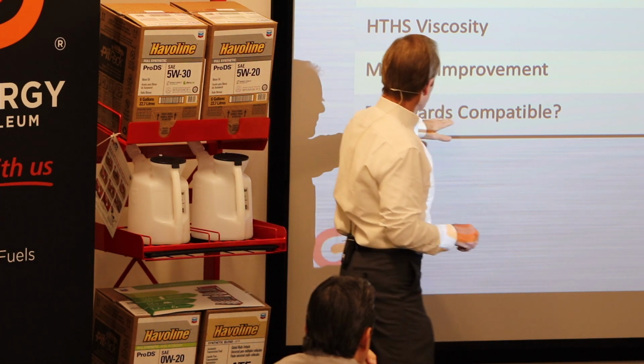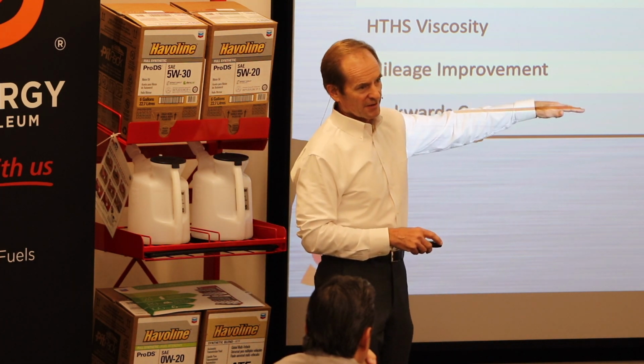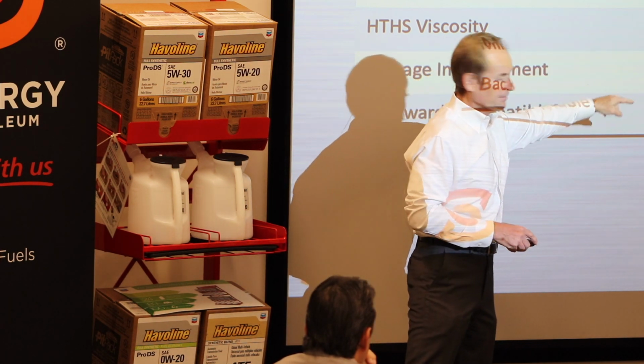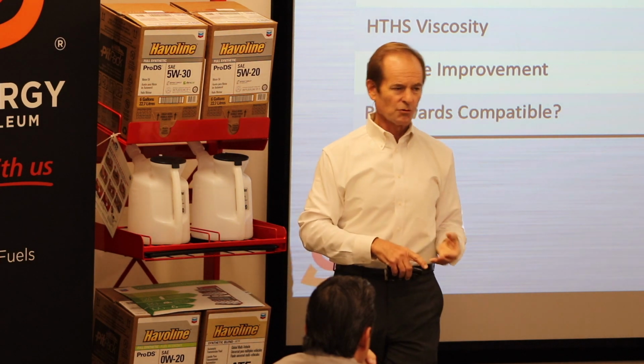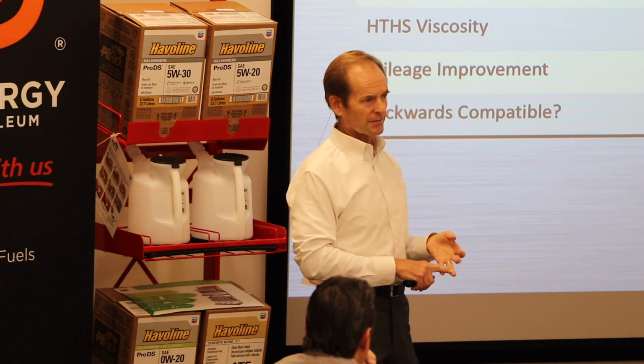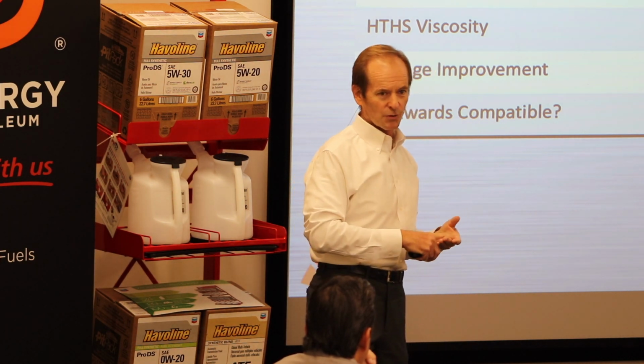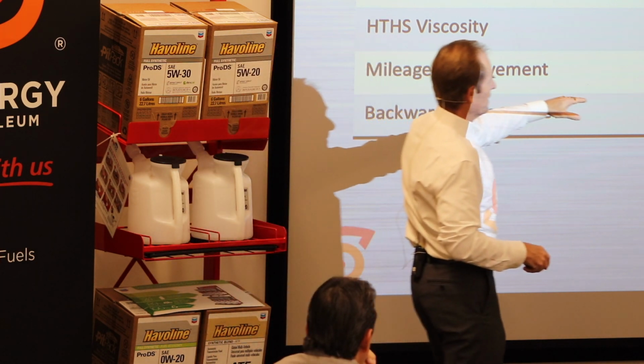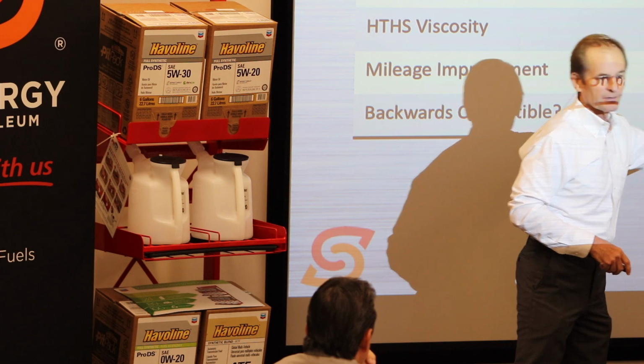And here's the important thing to note about CK4 and FA4 oils. Our CK4 oil, right, is backwards compatible. You can use CK4 where you used CJ4 or CI4 or CH4, anywhere on down the ladder. Okay, CK4 is backwards compatible. FA4, not.